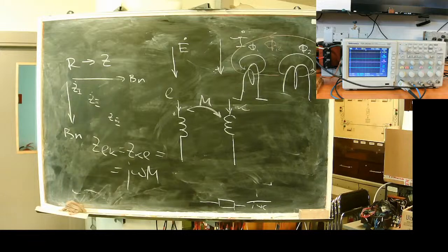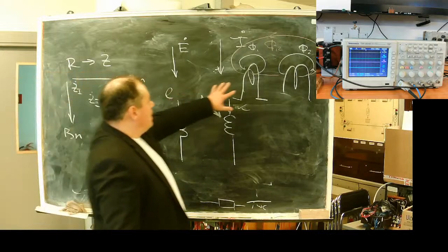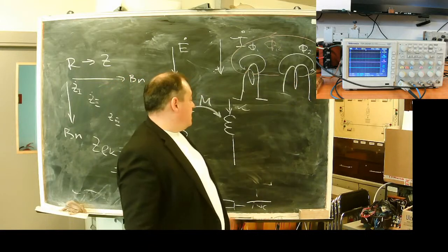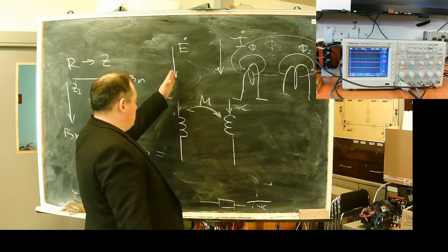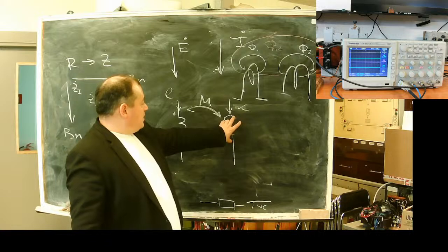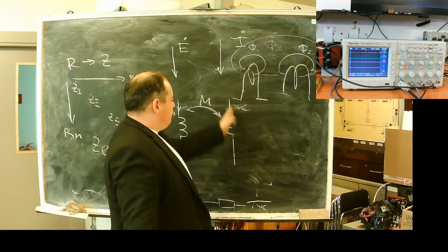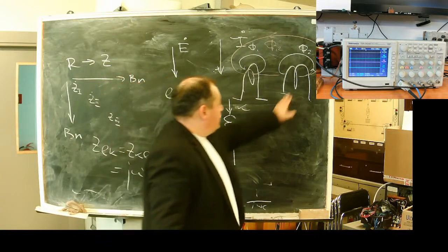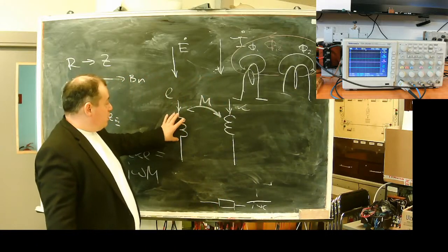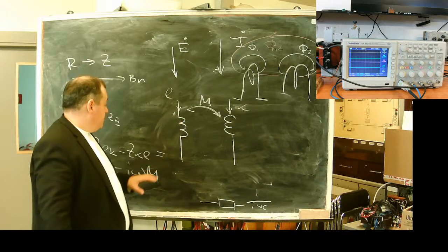You can account for the additional voltage drop from the inductance. Current in this coil induces voltage in the secondary coil. So if current flows here, we will see an additional voltage drop here. And in opposite, current flowing here induces an additional voltage drop in this network.